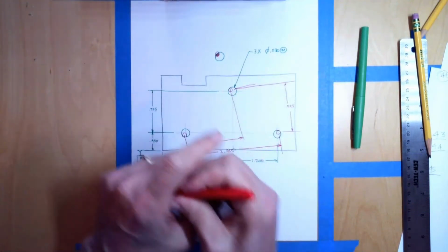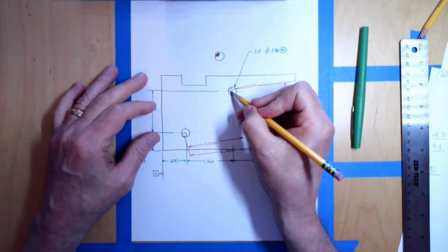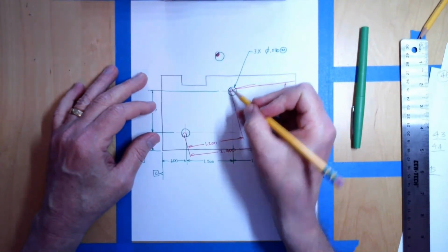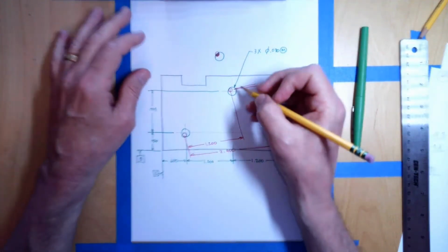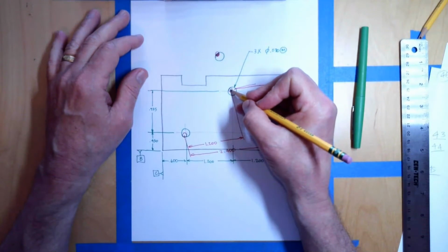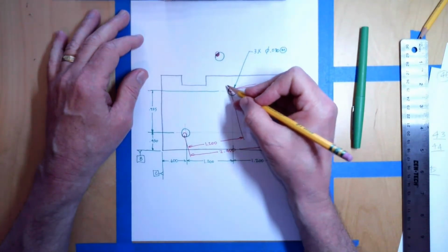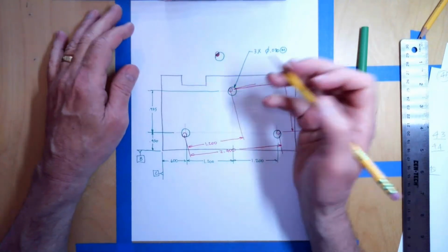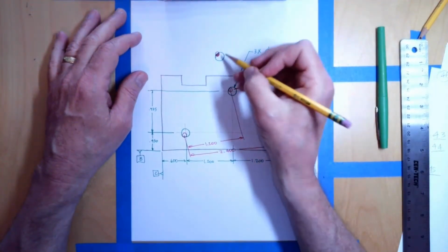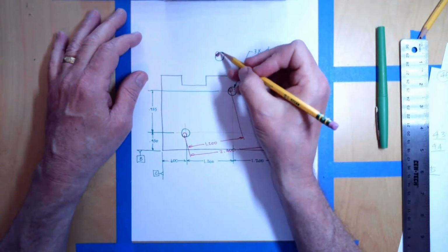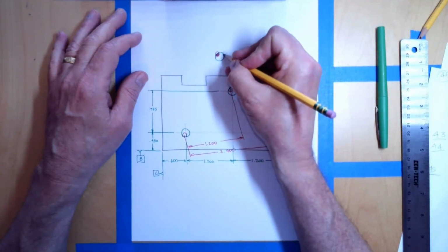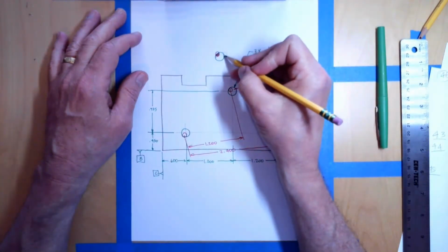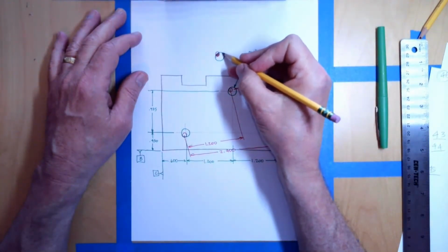Okay, so just to make things a little bit more understandable, I've made sure that my feature locating tolerance zone is always within my pattern locating tolerance zone. That way, I never have a situation where the center of my hole is outside of the boundaries of both. But in point of fact, I could have my feature locating tolerance zone in such a position out here so that most of my feature locating tolerance zone is outside of this, provided that the center of the hole, the axis of the hole, is not outside of the green.